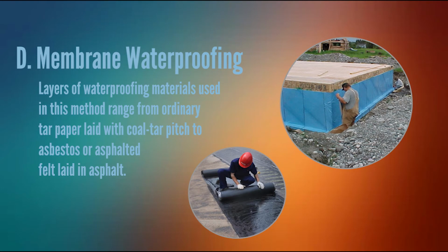And the last one is membrane waterproofing. Layers of waterproofing materials used in this method range from ordinary dark paper laid with coal tar pitch to asbestos or asphalted felt laid in asphalt.